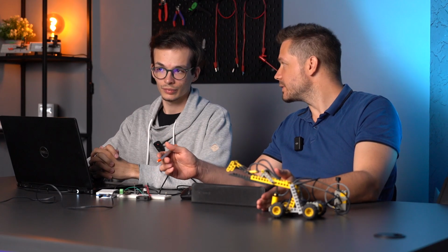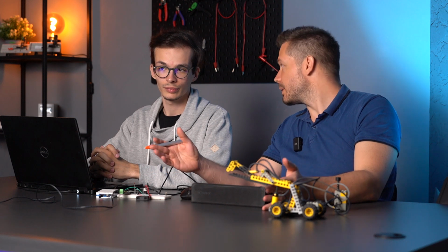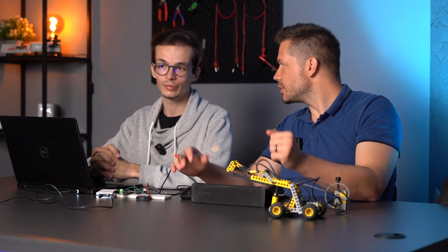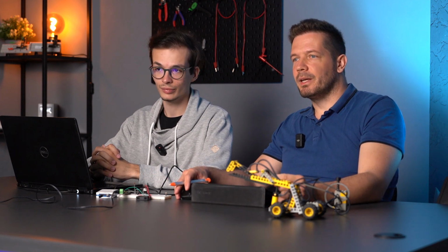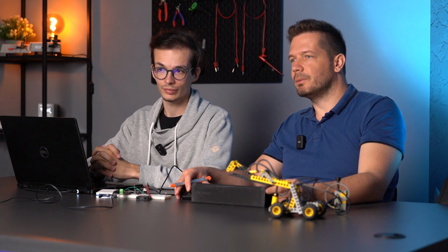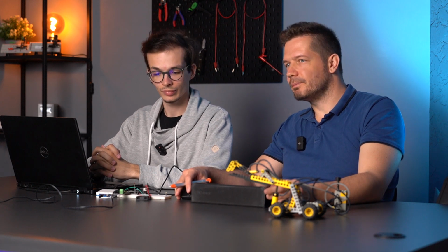For example, I know that I need to apply 12 volts if I want 1000 rotations per minute on the motor shaft and 6 volts if I only want 500. Now, these were just random numbers, of course, but in this way, you need to know your system and you need a model. It's very important to note that the interference from different sources can also affect the process, for example by changing the load on the engine. If we don't know these in advance, we won't be able to avoid their effects. And this, among other things, will make it necessary to use closed loop control. But for now, let's stick to open loop control.